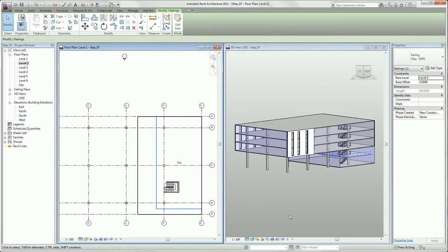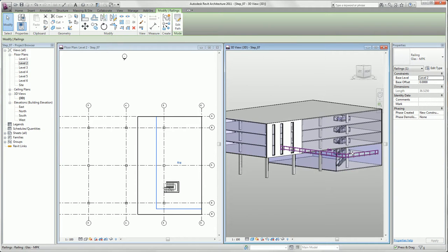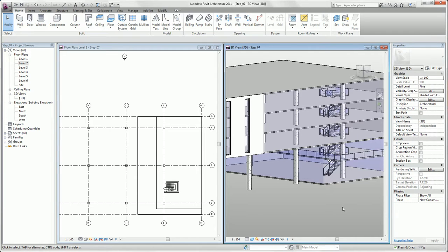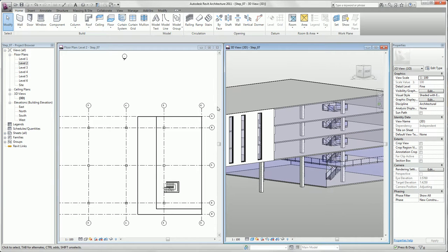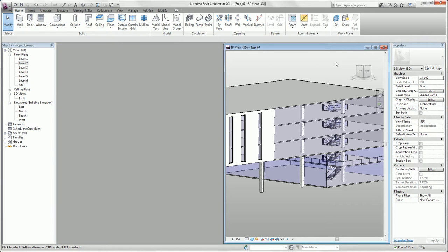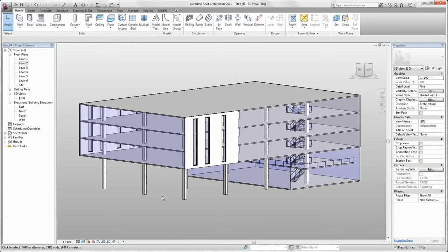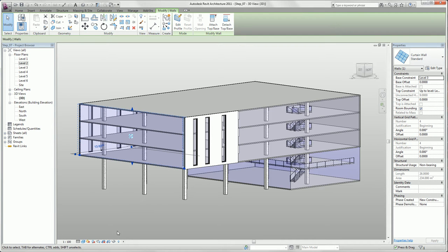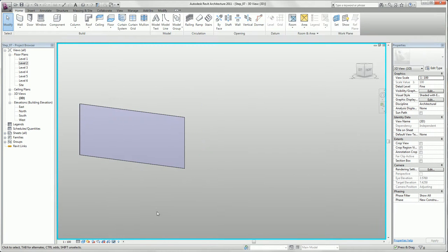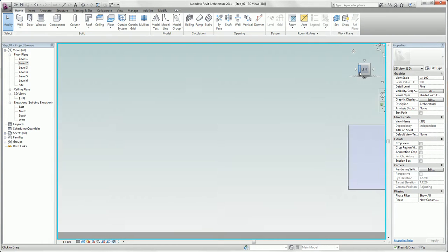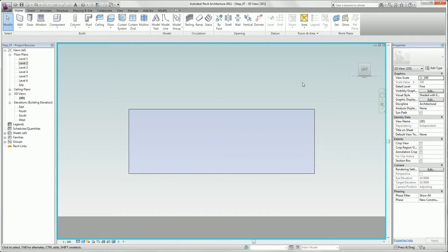In our 3D view, you see here our brand new railings. Now we close our second level view and maximize our 3D view. Further, we want to create a custom curtain wall, so we select our front facade and we use the sunglass tool and select here isolate element, and we use our view cube to switch into the left side view. Now we switch in our home tab and select curtain grid,